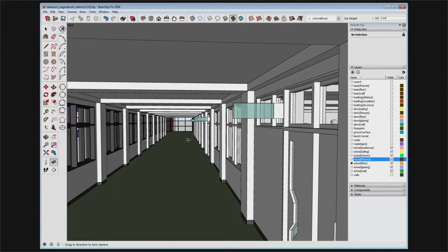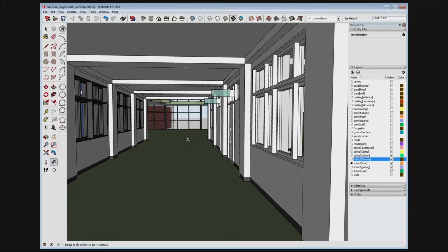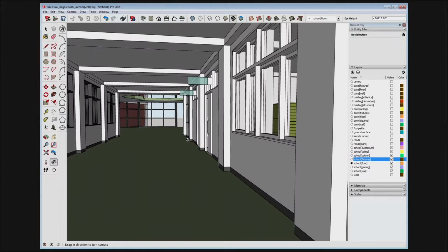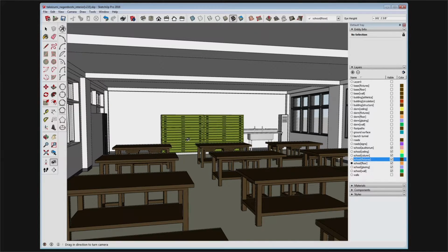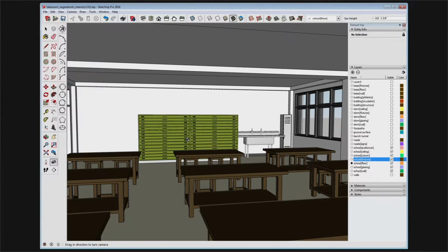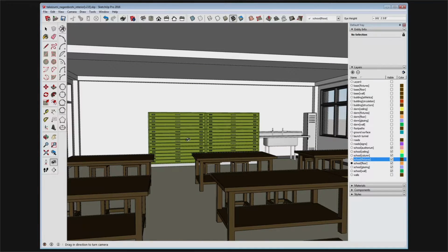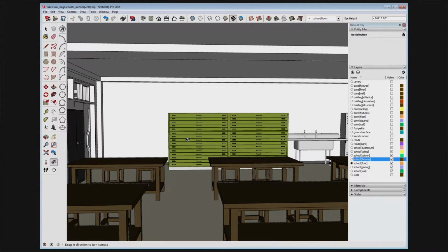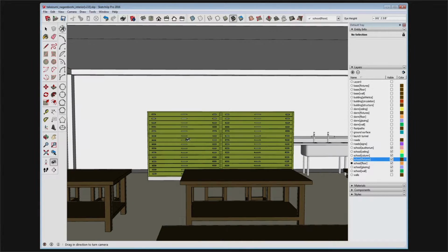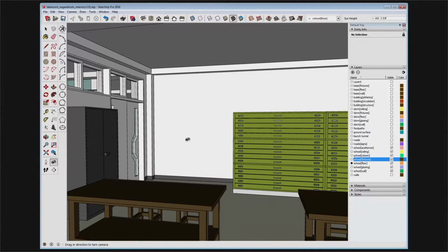And another drawback of using 3D, depending on what software, is what sort of things you can draw. Like SketchUp is good for flat, square things, but for any sort of organic material, you know, plants, trees and stuff, it's not. So that's one of the things I'm putting in post-production, but there's other 3D software programs that are better at rendering that. So it really all depends on what sort of environment you want to create, and at what point in the workflow is that done in the 3D software, and at what point is it done in your post-production.